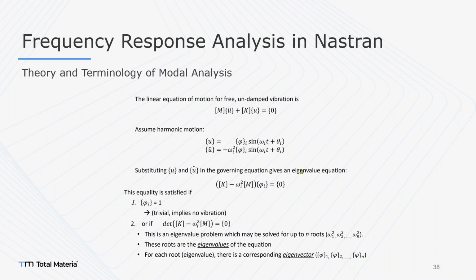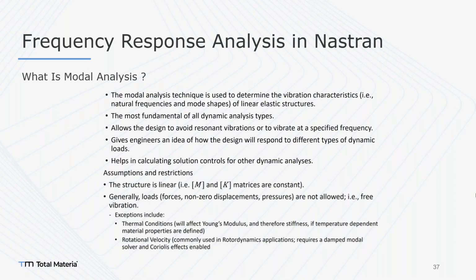Yeah, you can say something about the relationship between them. We can assume that an analysis can approach a dynamic solution or a static solution; there are really big differences. Just by looking at the modal shapes and the frequencies you extract, you can say that this needs to be a dynamic explicit solution, or this could be a static solution at the end.